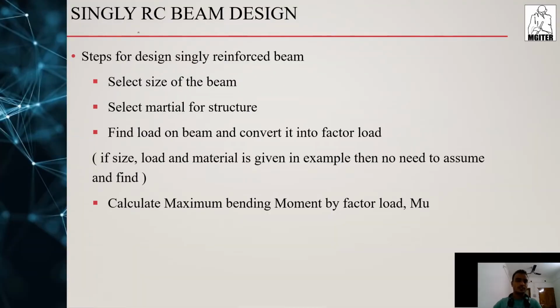Here are the design steps of a singly RC beam. For the design of a singly RC beam, first of all we have to select the size of the beam. Then after that, select the material of the structure. Then find the load on the beam and convert it into a factored load.